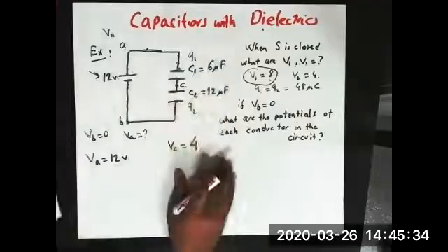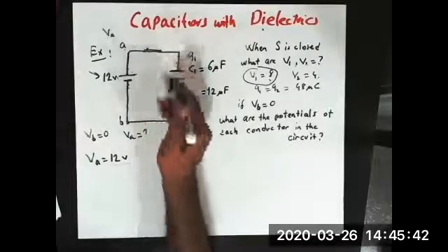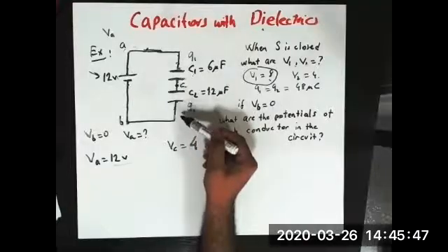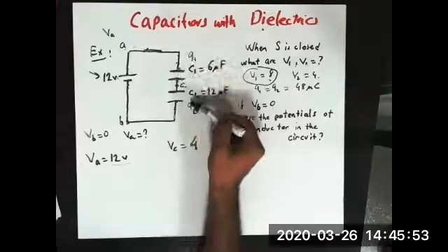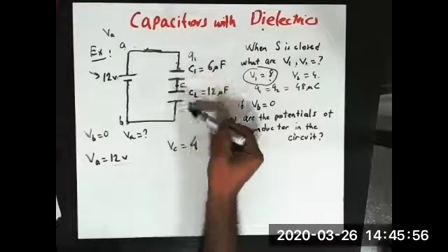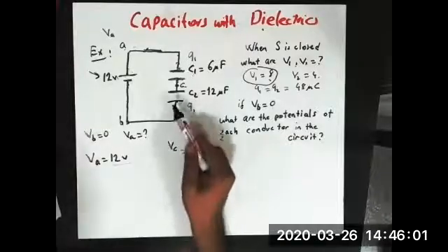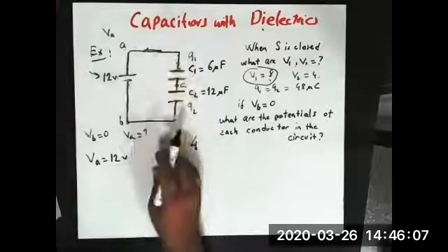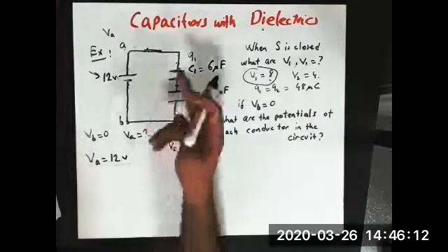All right, so what you have learned from this example is, first of all, that if capacitors are serially connected to each other, whatever the number of capacitors, the plates of every capacitor must have the same charge. All the plates must have the same charge. This is one thing you learn. And the next thing is how to find the conductors in a circuit. This is the way to find the conductors in a circuit. And this circuit has 3 conductors.